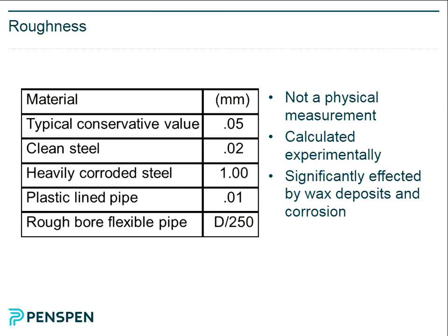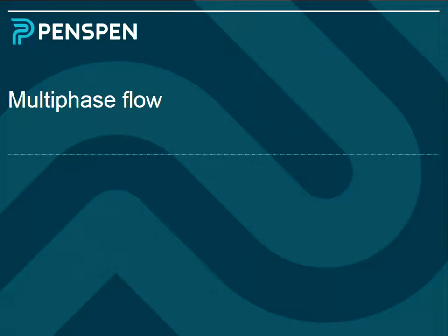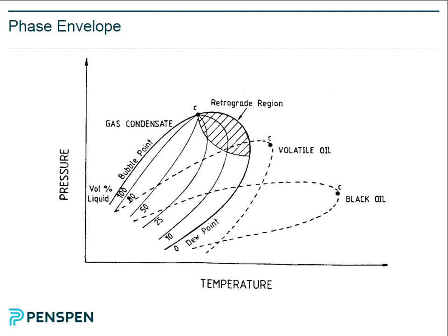Disadvantages: you have to have gas compression. If you talk about an offshore platform, you've got big, expensive compressors on an offshore platform, so there's costs. You're going to have to completely remove the water, because obviously water and high pressure would form hydrates, so you need to completely dehydrate your fluid. And also, if you think about a dense phase line, how do you actually start it, shut it down and start it up?